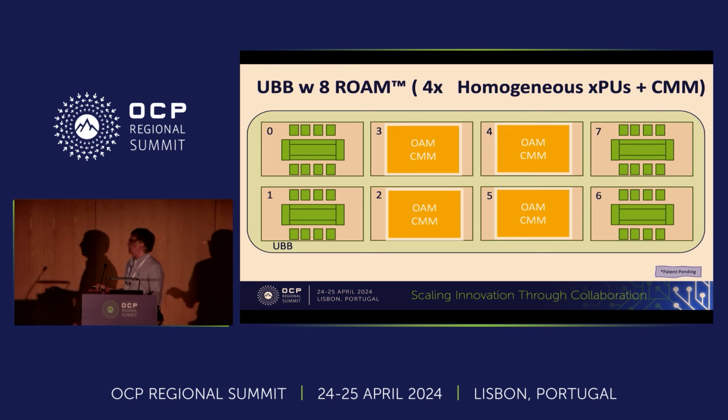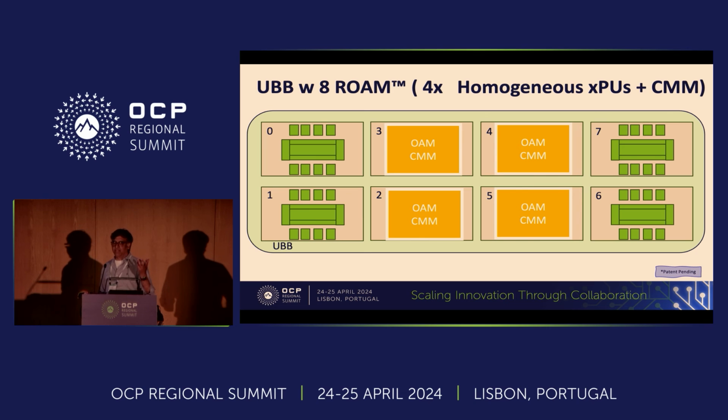The other thing one can do is think about a new type of memory chiplet, which is UCI based, but could fit into one of these slots. And that would have very high bandwidth, which could be 256 or 512 gigabytes. But it might be limited by the actual DRAM. DDR5 could be a single die about 8 GB. So those could be two options, but there's so many other solutions where there are CXL-based modules available.